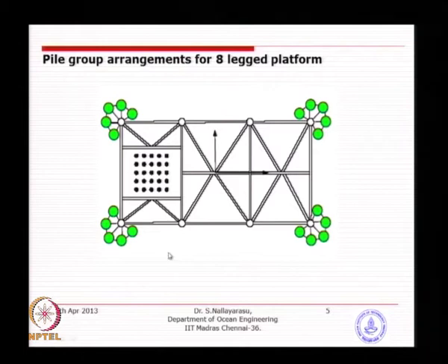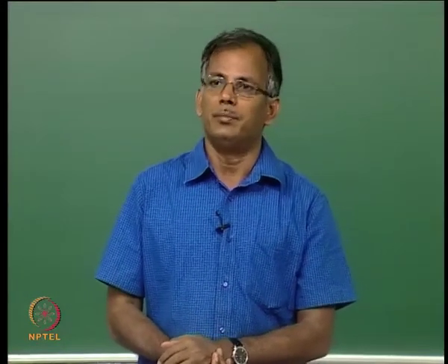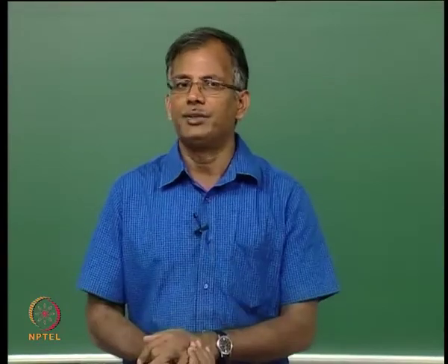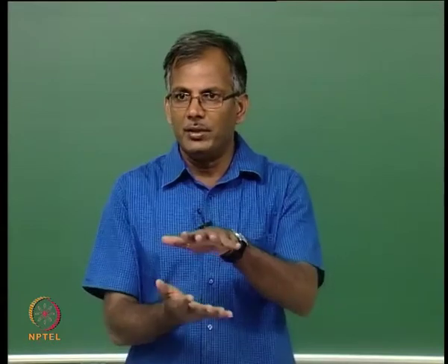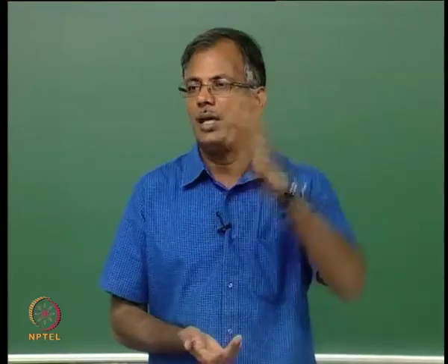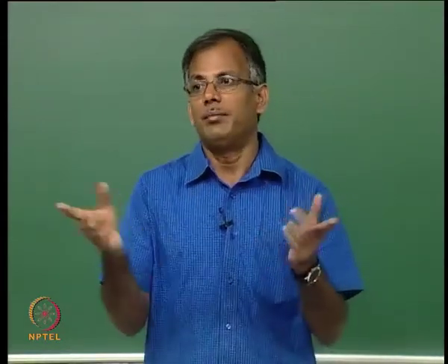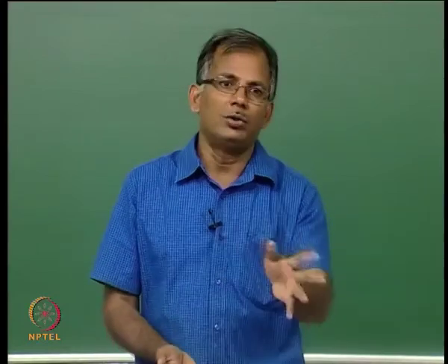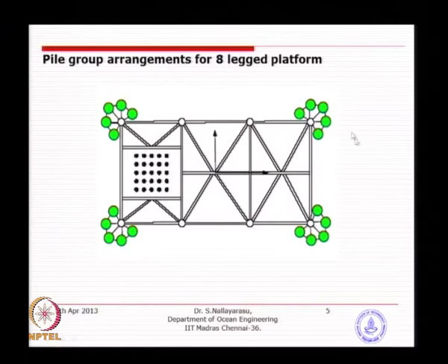In some of the platforms, cluster pile like this, you see the piles are distributed around. When you go for this, basically when you are not allowed to go beyond a certain depth, because you may have a very hard layer like sand, or you may have rock. So in such cases limit the penetration, increase the diameter or increase the number of piles. Increasing diameter is not a very good idea because you may not be able to install. So increase the number but reduce penetration and also reduce the diameter. So in such cases you will see what we call cluster pile.